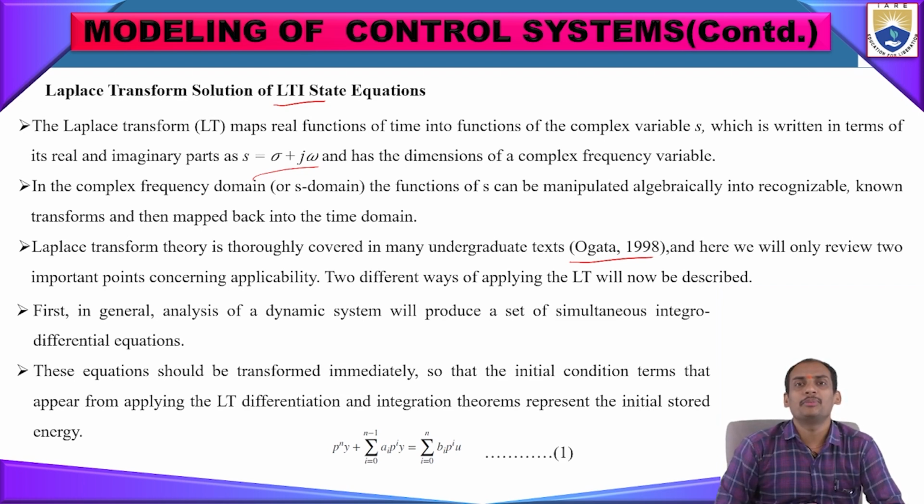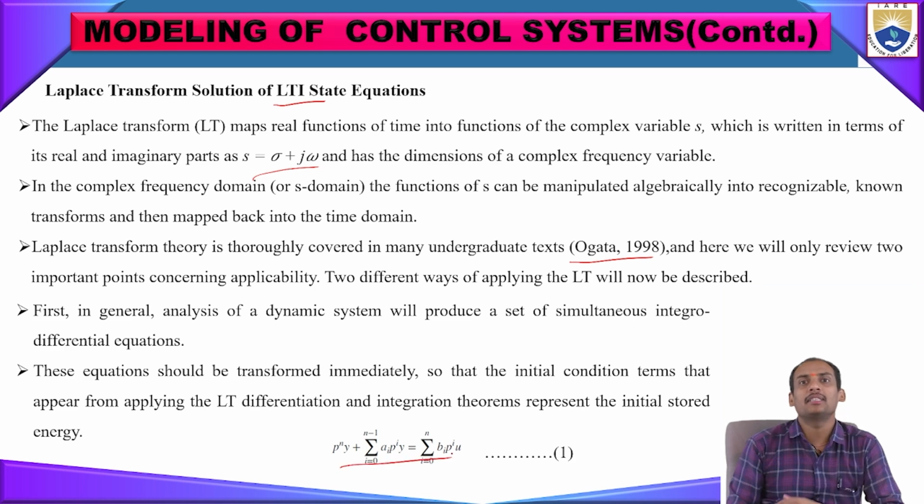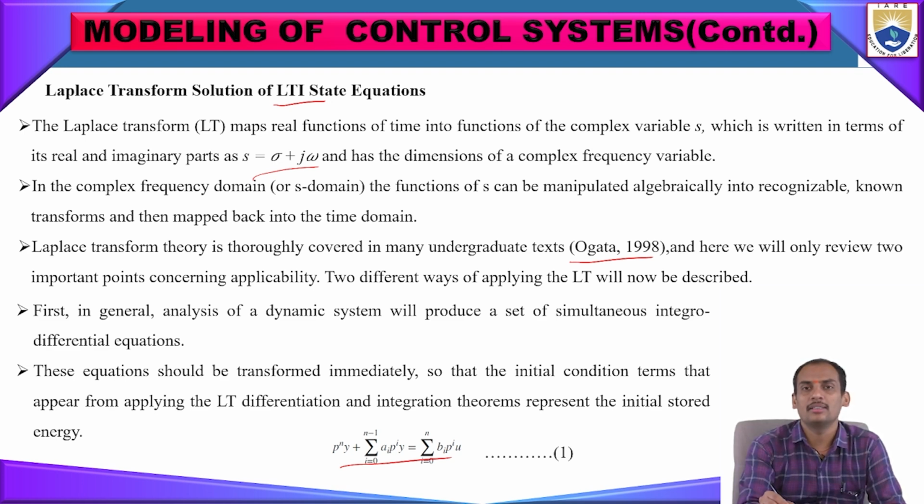These equations are transformed so that the initial condition terms that appear in the Laplace transform of differentiation and integration terms are represented in a single stored energy equation. If you remember this equation: the summation of i equal to 0 to n of a_i p^i y will be equal to the summation of i equal to 0 to n of b_i p^i u.